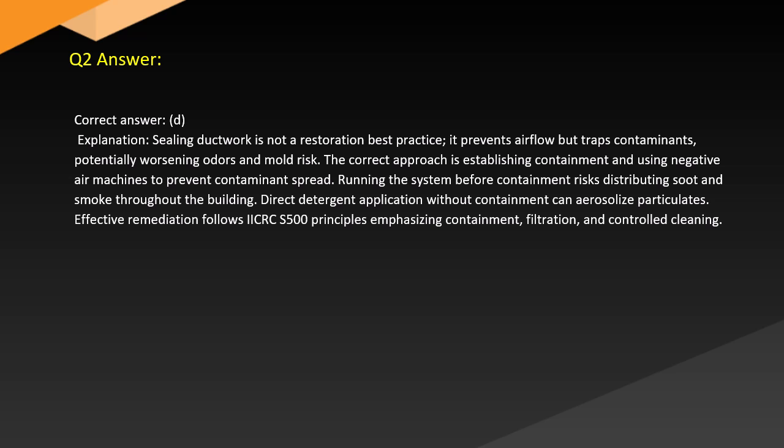Running the system before containment risks distributing smoke throughout the building. Direct detergent application without containment can aerosolize particulates. Effective remediation follows HVACR principles emphasizing containment, filtration, and controlled cleaning.